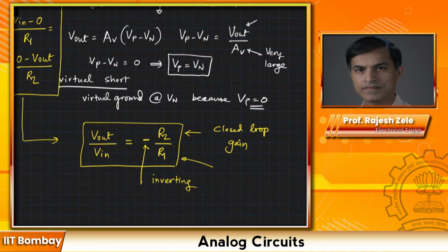This way of doing amplification is very popular even in integrated circuits, because there we may not be able to get the exact absolute value for each resistor. Meaning if I choose a value of 1 kilo ohm on a chip, then I may get maybe 900 ohms or I may get 1.1 kilo ohm.